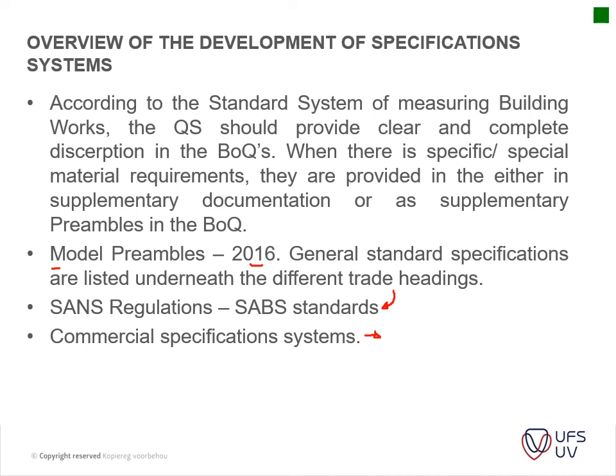So one would incorporate those standard specifications in your tender document. So it's just a commercial specific specification. Another example would be a specification on paintwork. Dulux have their own application specifications, how it should be applied, the moisture content of the walls should be a certain percentage, and that specification is then incorporated in your tender document.